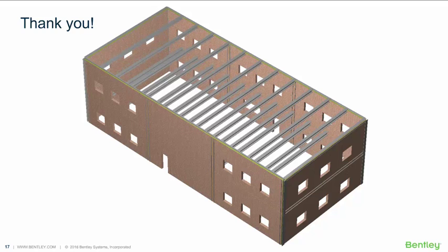There's another one here about joints in the CMU wall. That's prior to calling the module to do your masonry design. In RAM Elements, there is a little tool that allows you to create what I believe is called Insert a Gap or something similar, that will allow you to pick whatever wall you have in your model and insert a little gap there that would be your actual vertical joint before going into the module. So this is prior to the analysis and the design in the module.